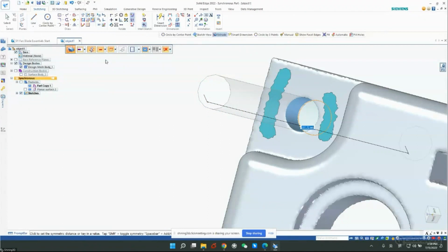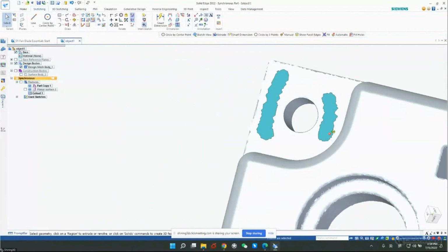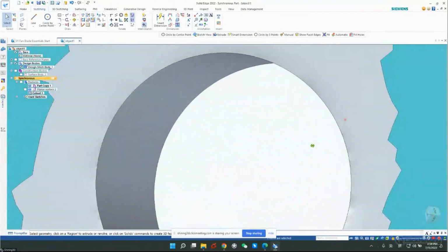And you can see on the bottom, it says you can tap shift to toggle symmetry or not. And you can hit the spacebar to change between adding or cutting material. And now you see I can use the sketch to directly cut the mesh object so that it will give you a pure rounded hole.